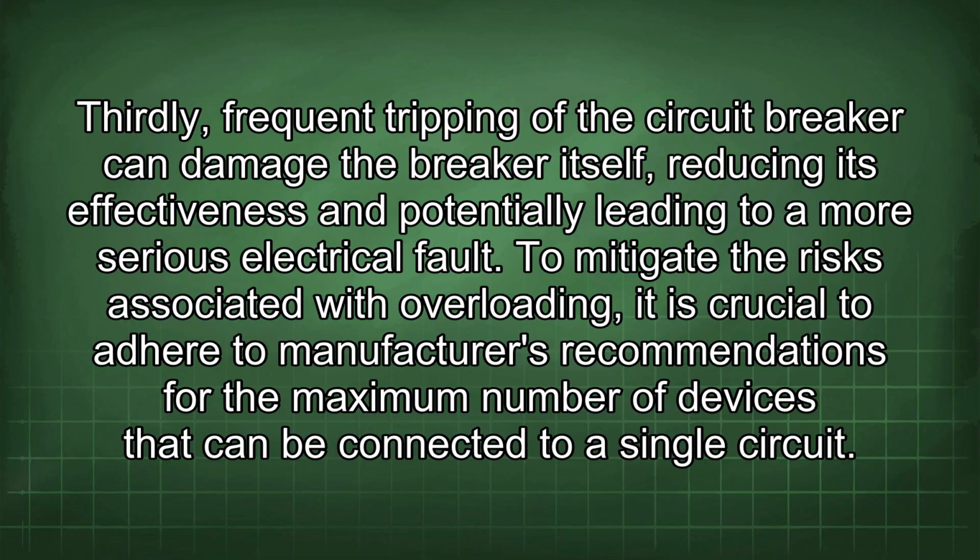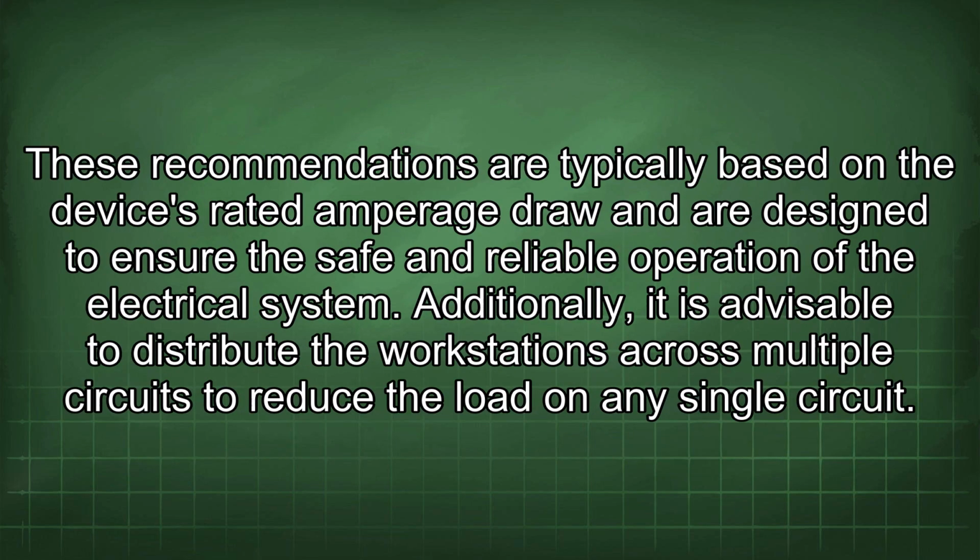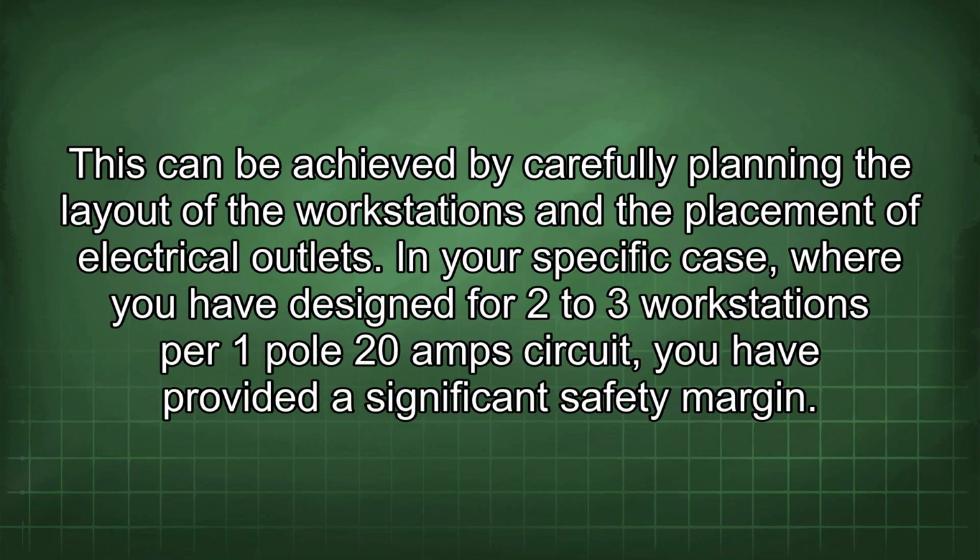To mitigate the risks associated with overloading, it is crucial to adhere to manufacturers' recommendations for the maximum number of devices that can be connected to a single circuit. These recommendations are typically based on the device's rated amperage draw and are designed to ensure the safe and reliable operation of the electrical system. Additionally, it is advisable to distribute the workstations across multiple circuits to reduce the load on any single circuit. This can be achieved by carefully planning the layout of the workstations and the placement of electrical outlets.